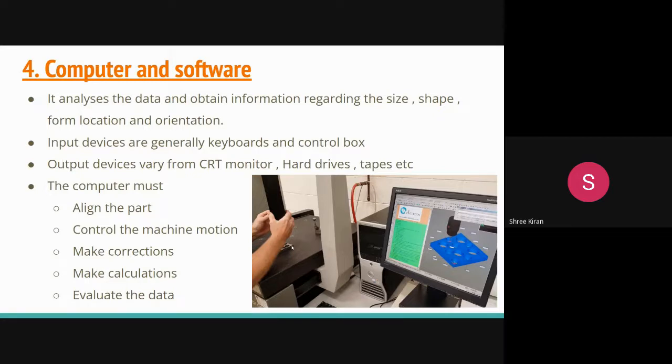The part is placed on the work table of a CMM at a suitable location, usually central to the machine axis, to access all the part surfaces to be inspected with the probe. It may be necessary to clamp the part to the work table depending upon the size of the part and the types of the probes used. If many similar parts are to be inspected, a reference location point is established with a reference precision cube or sphere.